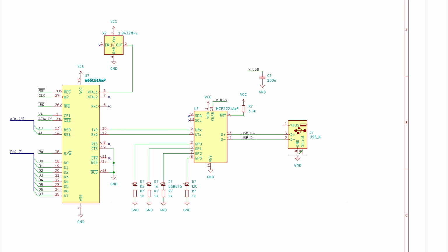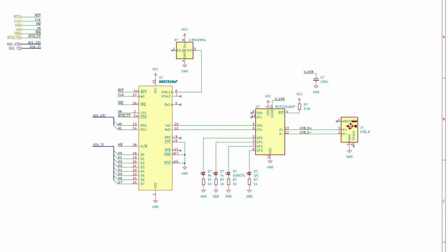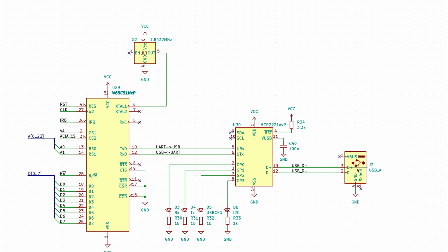We have to connect the ground, and because this is going to be a device, we shouldn't be connecting the shield of the connector. And then we're not going to be using the voltage provided by the USB ports, so VBus is also a no connect. Okay, so one small mistake. This should be a USB-B connector, not a USB-A.